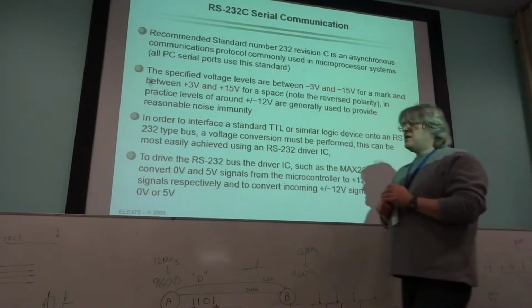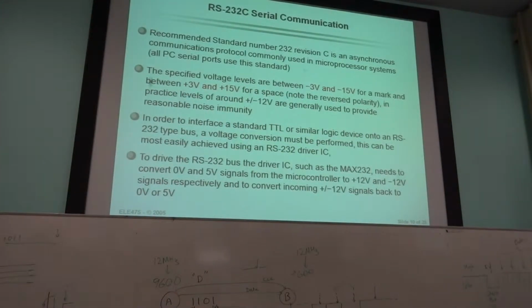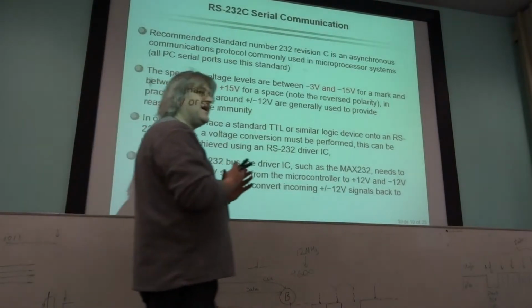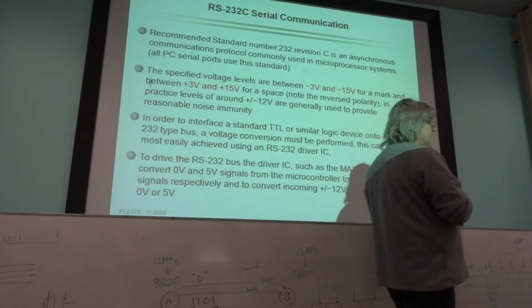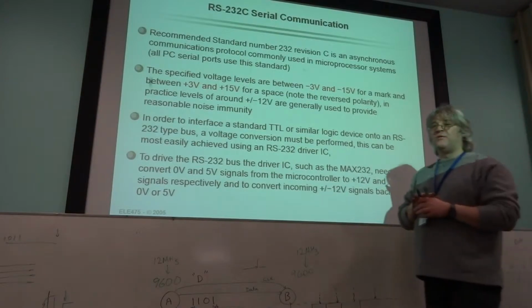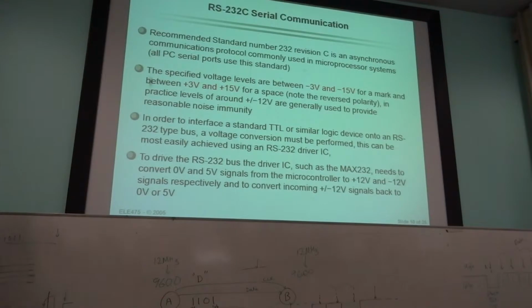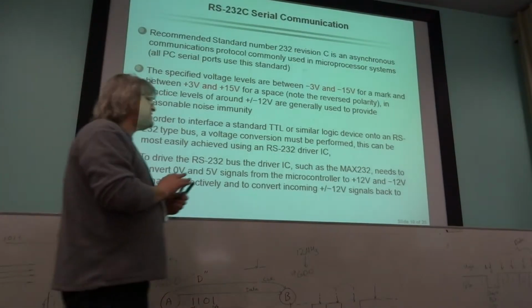Okay. You are expected to know the difference between synchronous and asynchronous serial communication. You'd be expected to know the difference between full duplex, half duplex, and simplex, and we need to know a little bit more about how serial communication works inside the 8051, which is what I'm going to do now. So the 8051 serial communication system is an example of an asynchronous serial communication system.